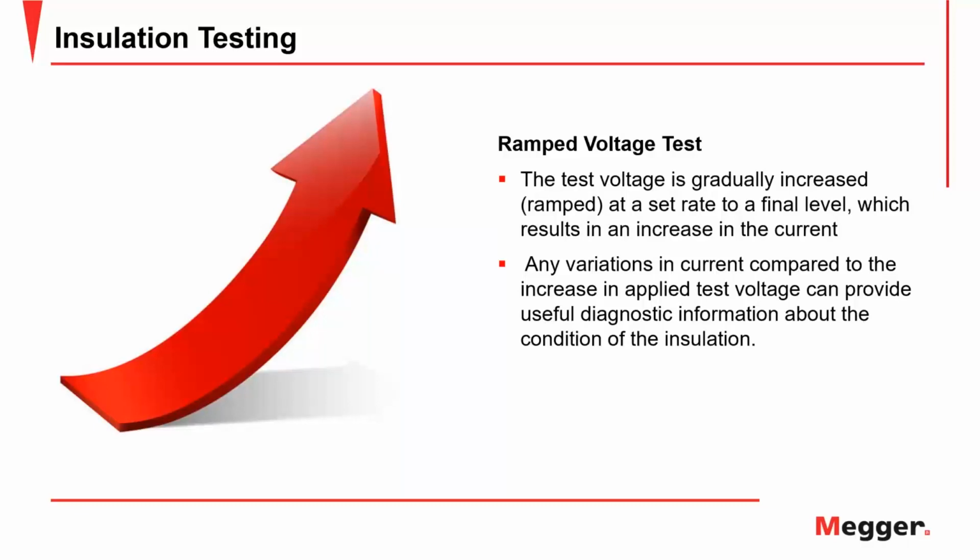If you have a relatively sophisticated tester that has a ramp test in it, you hit the button, and it starts to apply the voltage 1 volt at a time. It will creep up 1 volt at a time, and it will store the reading at every voltage up to the top voltage that you selected.